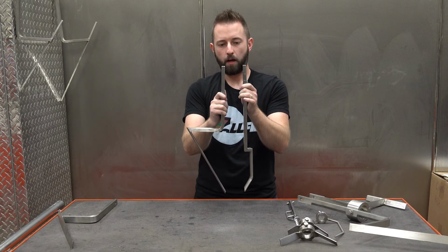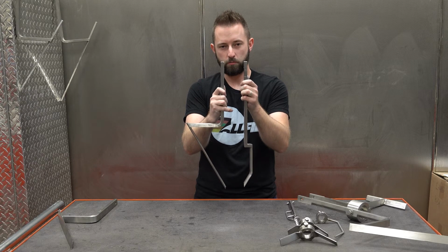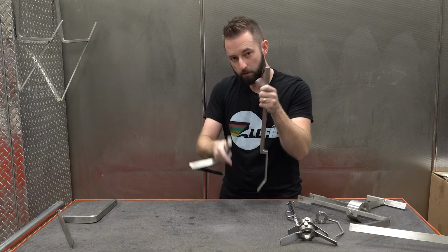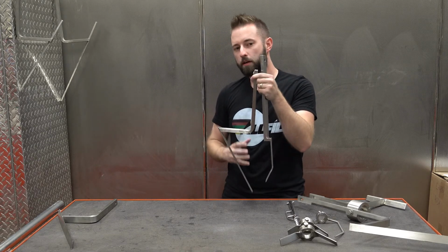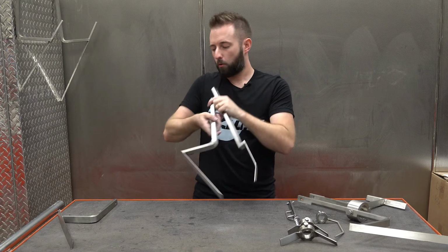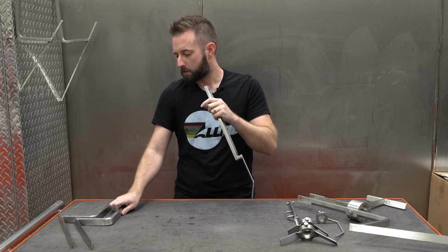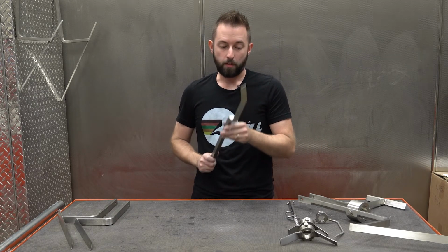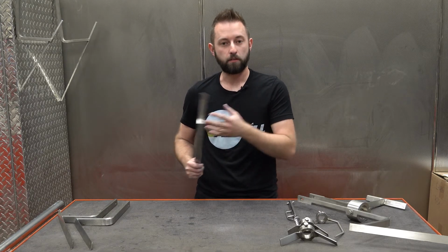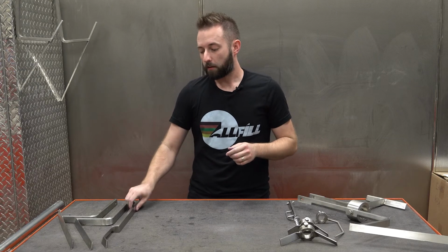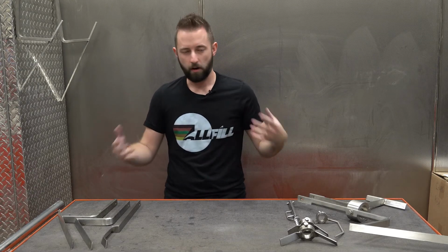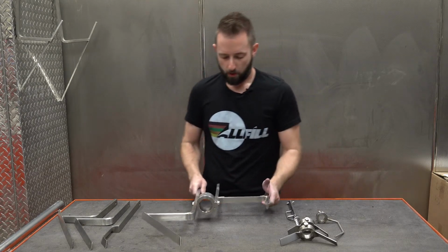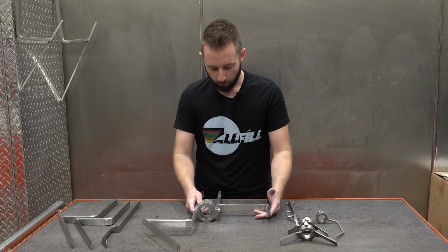But essentially now you've got a combination where the auger is in between these 2 agitation blades, and these both rotate, this helping with the rat holing issue in the center, and this helping to grab that product on the outside edges of the hopper and drag that forward. So it's a very custom thing when it gets into difficult products, light density products, and we have a lot of different variations that we can do to kind of attack these issues. And again, we're going to do specific highlight videos showing these being implemented in various different settings and different issues that we have here. With that, speaking of double agitation, I want to explain a couple of other oddball agitation blades that we do have.